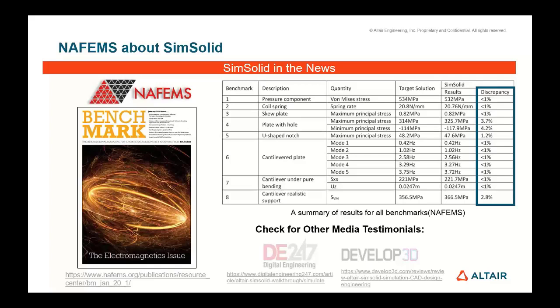Perfect. Yeah, exactly. So one question: is it possible to use composite materials with a specified layered pattern in SimSolid? To that detail, no. You'd have to use OptiStruct and HyperWorks. The only thing that you can use in SimSolid are orthotropic materials.